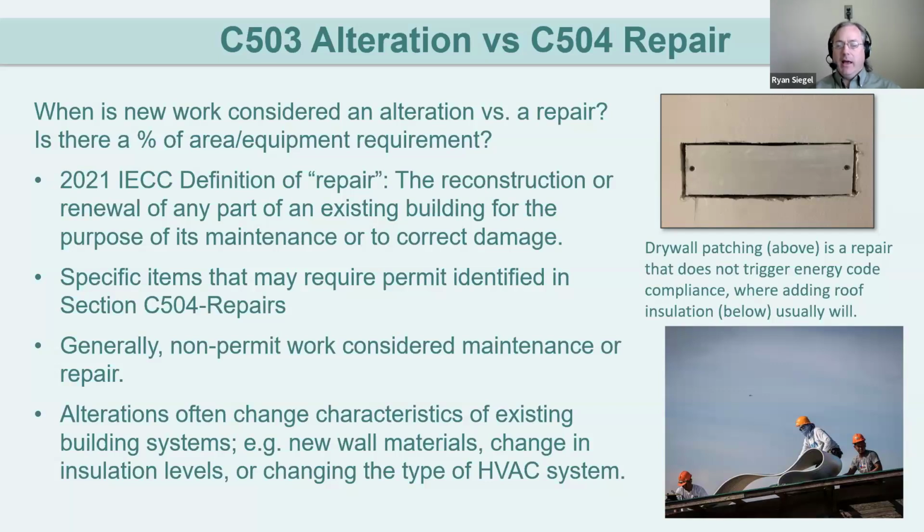Alterations, again, looking at, are we changing the characteristics of the building? Are we going to be changing or adding insulation? Are we changing the type, size, efficiency of the HVAC unit? With just replacing an HVAC unit, people will say, well, it was like for like. However, you probably have improved the efficiency or you have made other improvements given that new unit. So that may be classified as an alteration. Again, replacing the blower unit, that's probably going to be a repair, not an alteration.